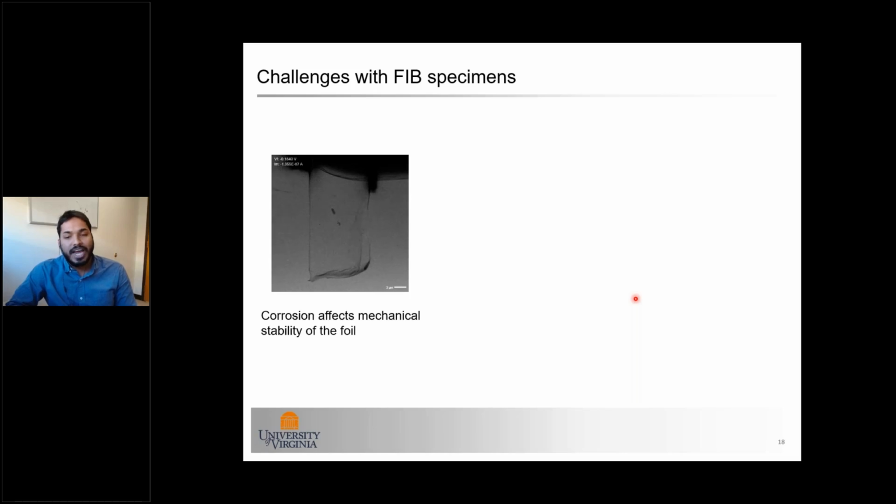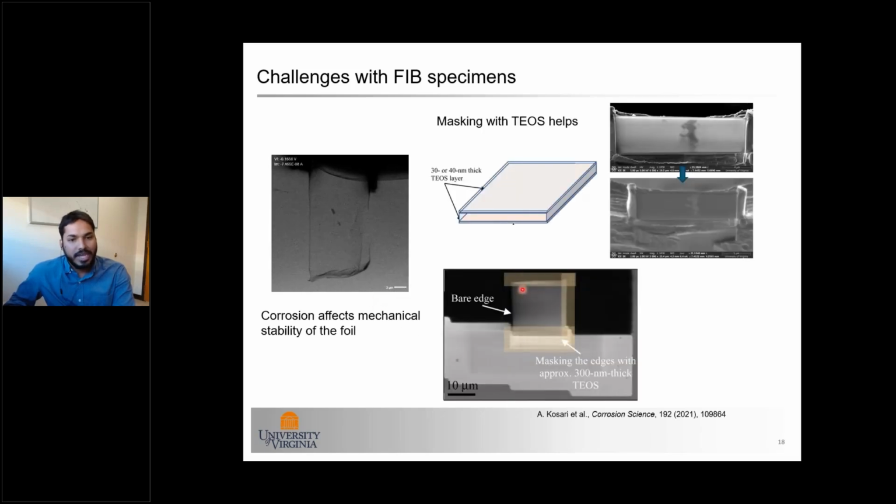So with the metal bridge setup, definitely we solved the electrochemical measurement related issue. But we had another issue with FIB lift out. As you can see, when corrosion progresses, the specimen gets crumbled, making it difficult to focus on one specific side. And for this, there were some suggestions from the community that it is better to have a relatively thicker lamella. Of course, that would limit the resolution of any features you want to see.